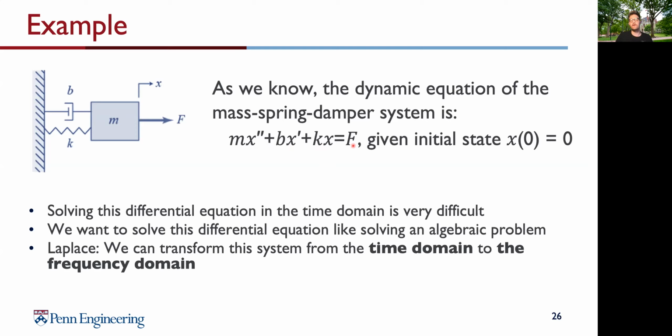And this equals the force. So we can set up these differential equations, but solving this in the time domain is super difficult. So we want to solve this differential equation like an algebraic problem. Again, we're transferring it from the time domain to the frequency domain. And then we have a polynomial we can easily solve.